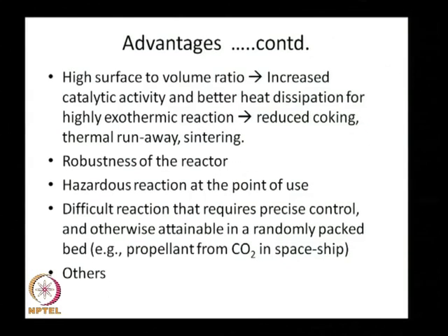Okay, advantages continued. When we go for a microstructured catalyst, as I said, instead of having a randomly packed bed, you can have a monolith, something like a honeycomb with internal walls coated with a catalyst, that we call a structured catalyst. There you can have high surface to volume ratio, which means increased catalytic activity and better heat dissipation for highly exothermic reactions.